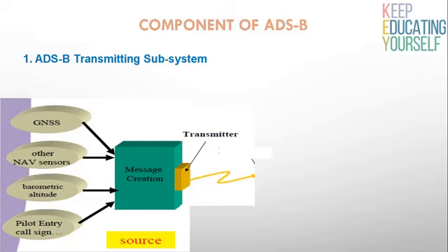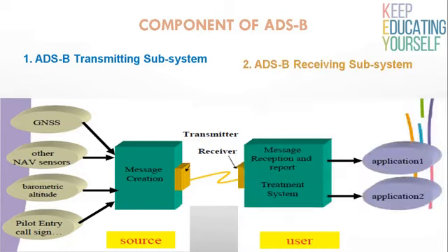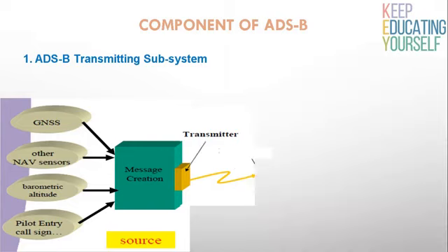ADS-B information transfer: call sign, state vector, three-dimensional position, height, altitude, airborne turn indication, navigation accuracy category, emergency or priority status to air traffic services, current intent, CDTI.